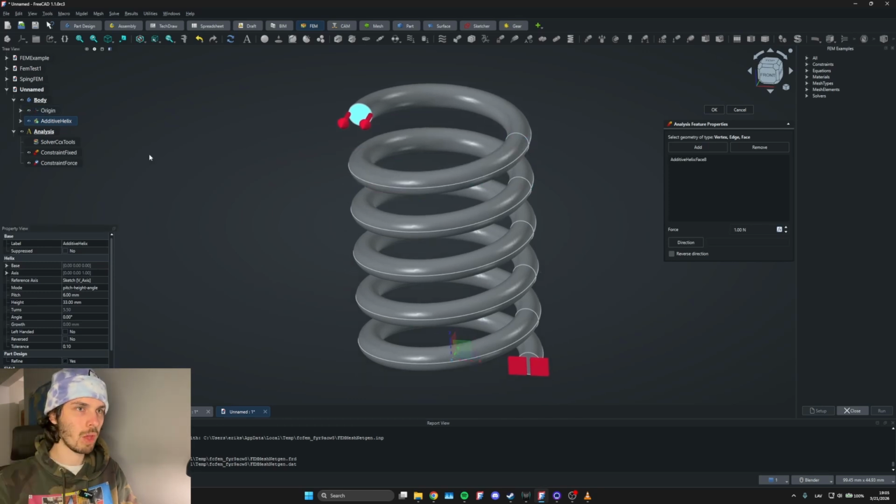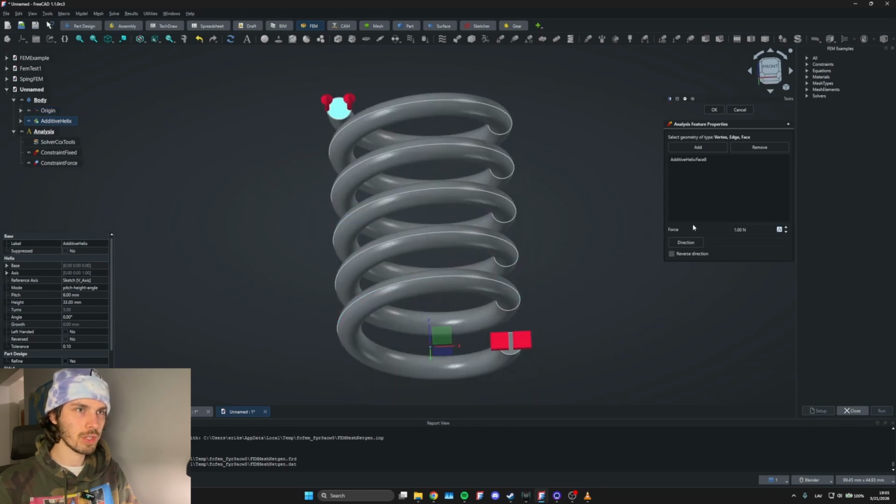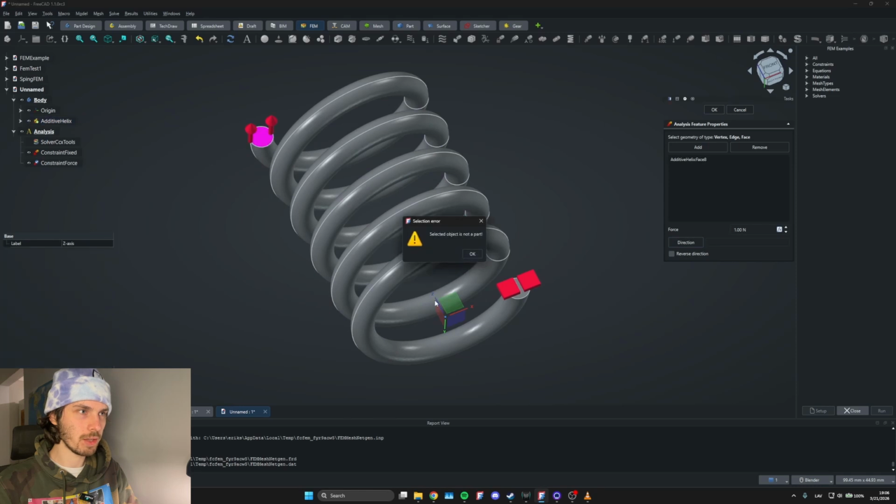But we must change it so it's like up and down. For that, enable origin, then over here on the right side, or left side, it might be, there's going to be a button for direction. You have to click on the direction first. This can be an axis or someplace on the part itself. So I'm going to click on the Z over here. Okay, maybe direction and then the Z. That's where it worked.